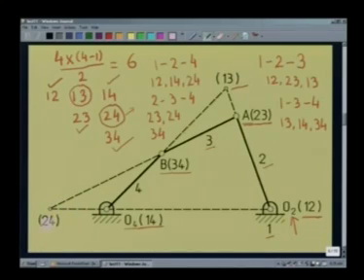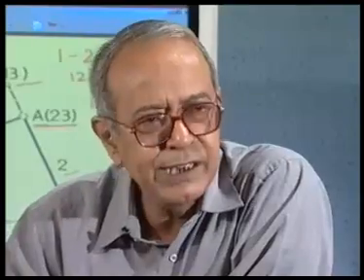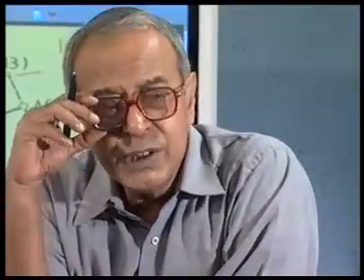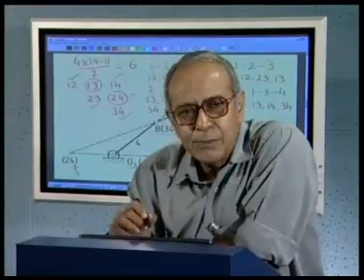As a result, we get the location of 2, 4 here, at the intersection of O2, O4 and AB. So, we determine some of the relative instantaneous centers just by inspection of the kinematic pairs, and the rest by application of the Aronhold-Kennedy theorem.